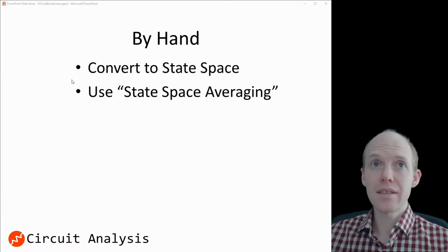And we do what's called a state space average of those two states proportional to the converter's current duty cycle. And the thing is, PSPICE does this first part, the converting to the frequency, but it doesn't have a way to do this state space averaging part. And that is essentially why we have to create a linearized model of our circuit.